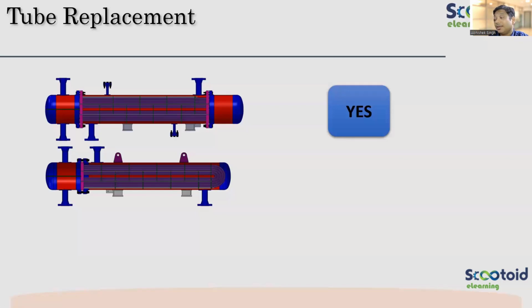So that can be really, really dangerous. Okay. So I'll not like to use this configuration if I'm having a fluid which is very dangerous to human life. Because leakage may happen, you know. The leakage happens from gasket, it will directly come out to the atmosphere. So I'll not do that. Okay.